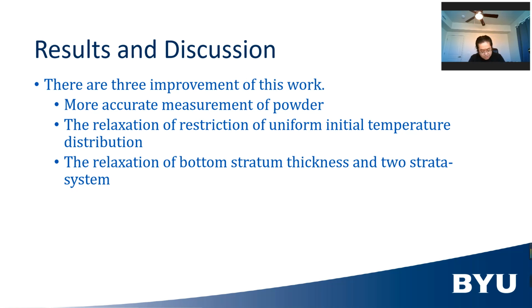At last, although in this sample the bottom has a semi-infinite thickness, we now can obtain analytical solution of any effusivity ratio between two strata system. This means the restriction in bottom effusivity is also relaxed. Also, it's really not difficult to use the same mathematical tool to solve multi-stratum PDE system. In this case, we can monitor multi-stratum system, and that is the powder bed of BJ printing process. This means the application of optimization on flash thermography not only expands the usage of flash thermography on a lot more scale, but also the success rate of BJ printing is increased and the yield is also increased.